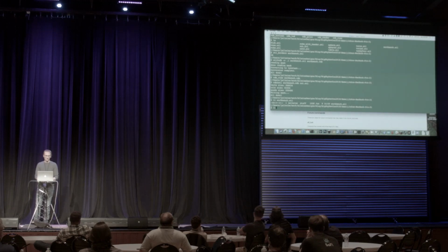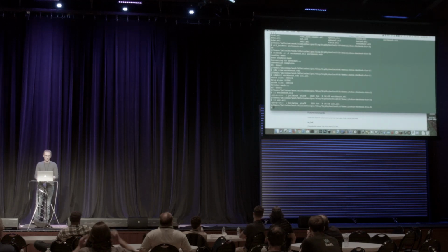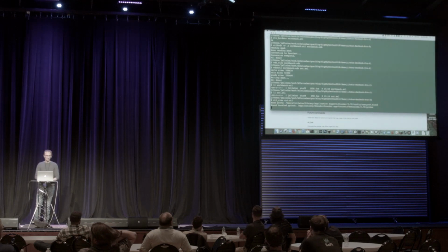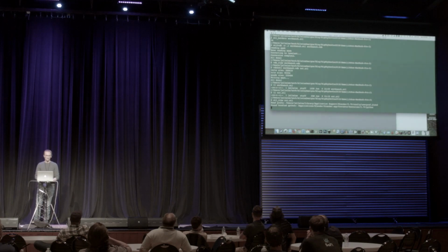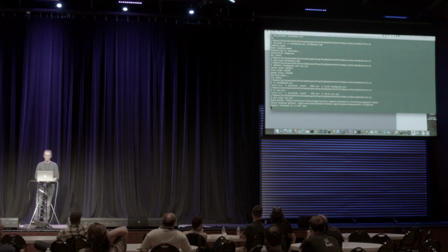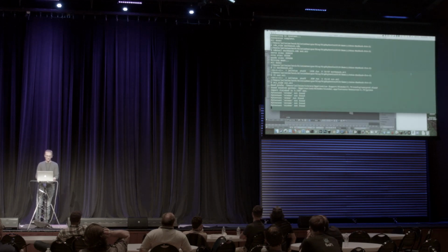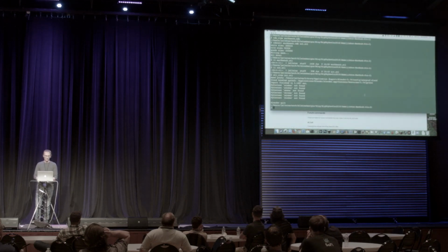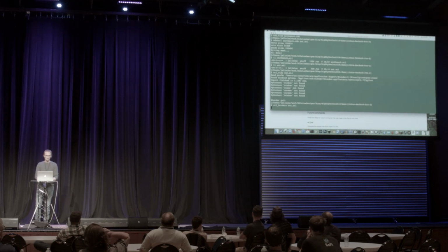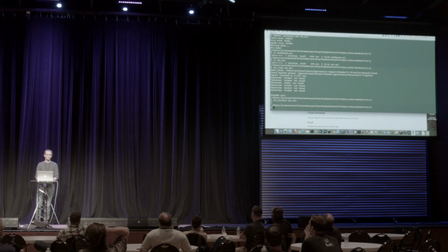If I look at the file size of out.stl, it's 25 megs. So it's not the ideal way to fix things if you can fix it in a simpler way, but this can be a brute force method to fix a model. And now if I do stl borders on out.stl, it's watertight.